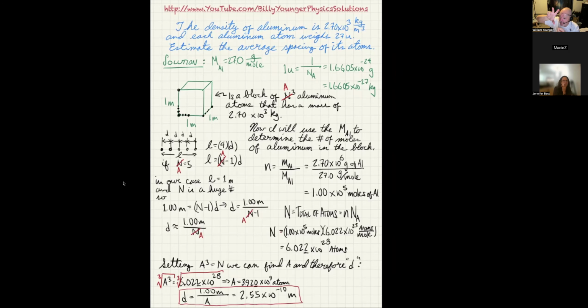So for however high that cylinder is, that means a different volume. So if you increase the temperature, the only way that thermometer can allow its alcohol to change its volume is by going up the little cylindrical tube, which is basically a vacuum above it. So it just moves its way up. So that's the way we make a liquid thermometer.